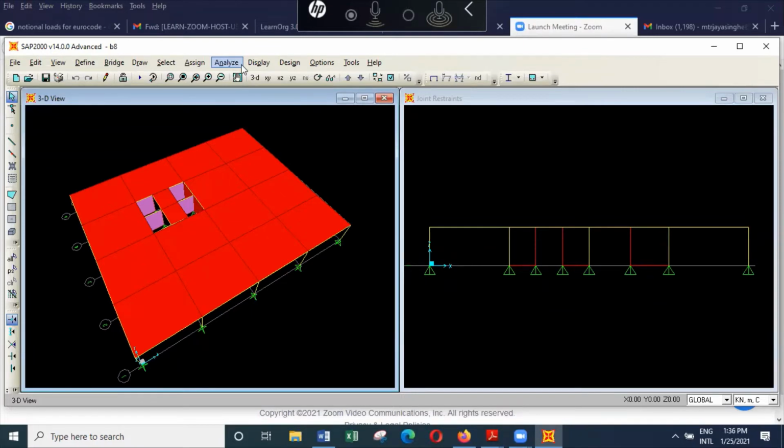Say we have a cantilever slab here. All the load on the cantilever slab will finally come onto this beam, so you can have an additional load on this beam due to the cantilever slab. Because a cantilever slab is a statically determinate structure, you can straight away determine the load transferred onto the beam. If you know that load, apply it as a separate load.